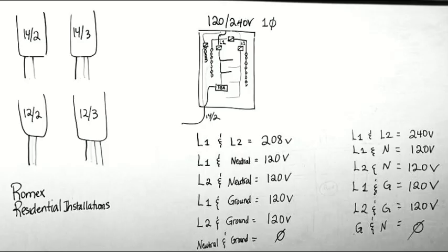As the wires get larger, now we use stranded. You guys used stranded yesterday, right? As the wires get larger, we use stranded because that makes them a little bit more flexible. If they're solid, it gets really hard to bend them, to make a hook, to fold them in the box.